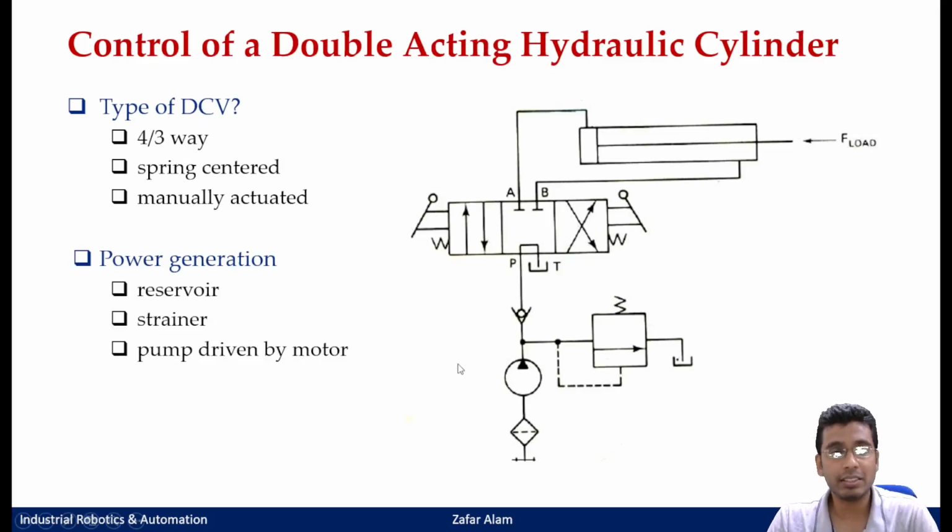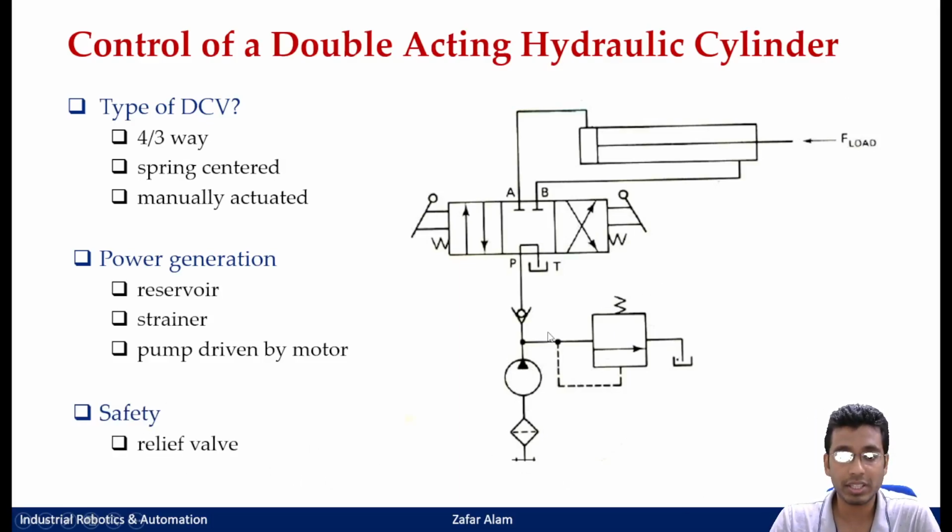Then again the power generation will consist of the same things here. So you'll be having a reservoir, your strainer and your pump, right, which is actually driven by a motor. After that, you also have your safety device here, which is your relief valve, as we discussed in case of control of a single acting cylinder.